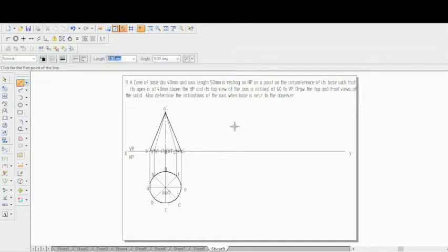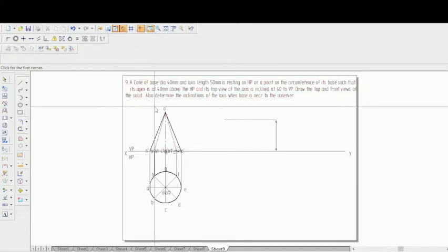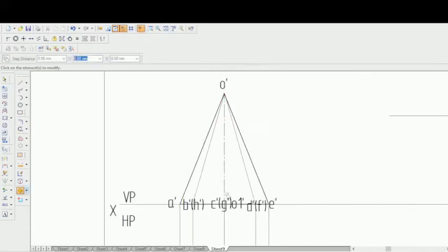That means we'll just have to draw a reference line, and the distance between the XY line and the reference line is 40 mm. So here you can see it is 42.58, so let's enter 40. Now first, move this front view. Just copy it, so see that copy is switched on. Instead of directly selecting it, let's zoom in and, using the control key, select only the lines.